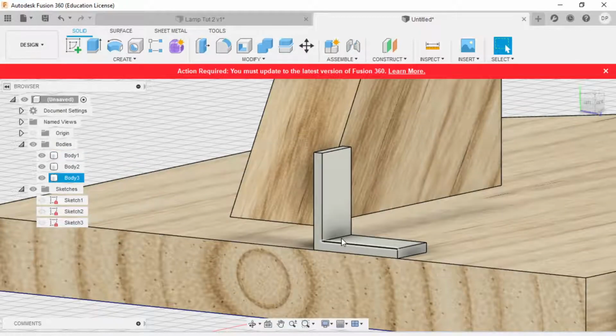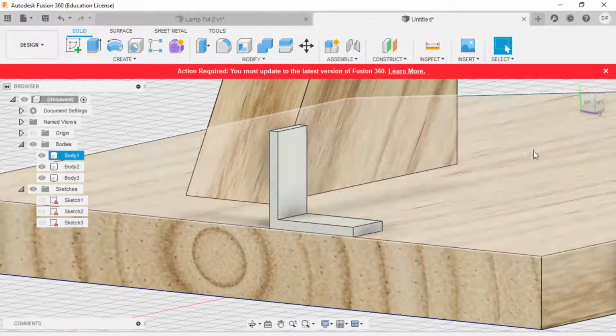This piece of aluminium that we made, because we aligned it, it's going to follow that surface as it changes. But this top vertical piece of the stand is not connected by an alignment, so it's not going to follow the thickness of the material. So we'll add another alignment feature. We will go and